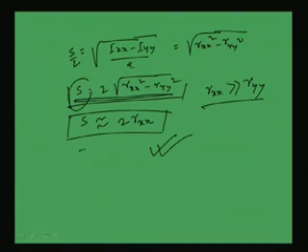If the load is concentrically acting, that means only compressive force is coming, then we can find out the optimum spacing, the spacing which will make the built up sections most economic. That can be found through this. Here we will go through an example to demonstrate how to find out the strength of a built up section.